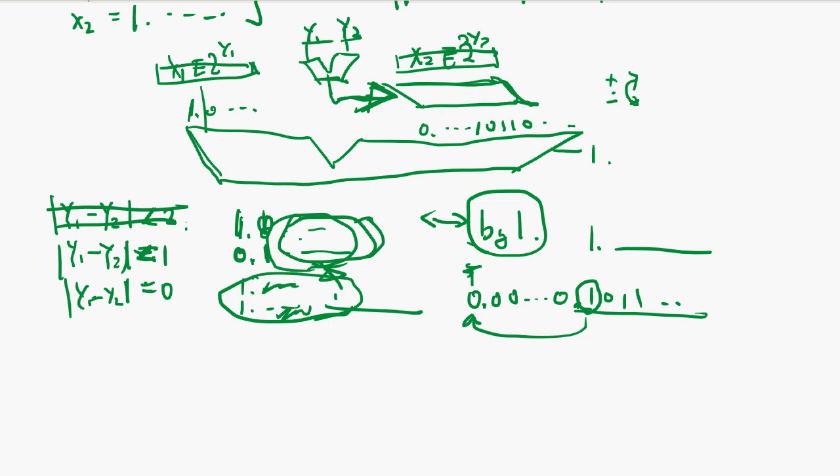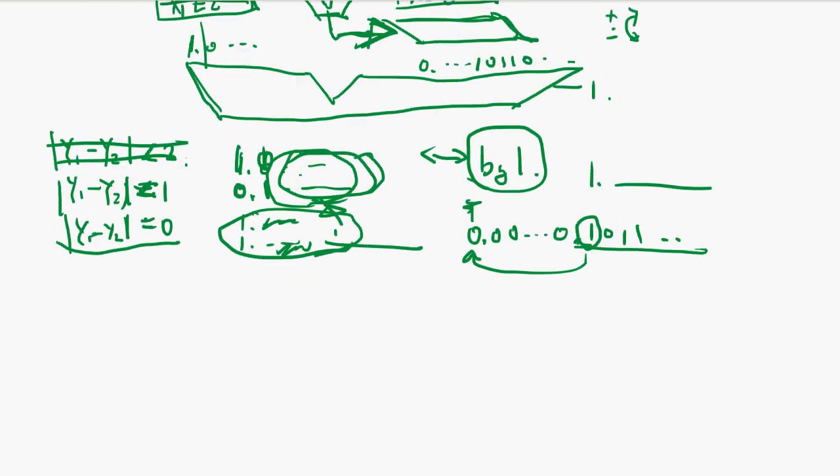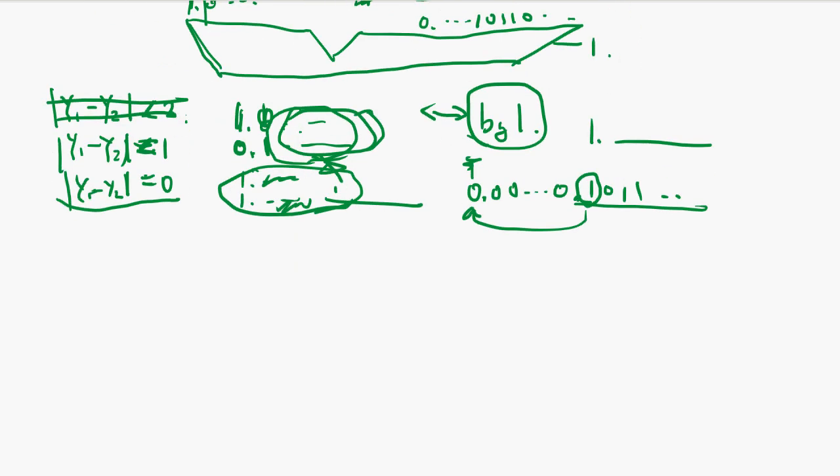So in this case, we have to worry about bringing this format back to the leading 1, the standard floating point format. So we need this leading 0, leading bit detection.